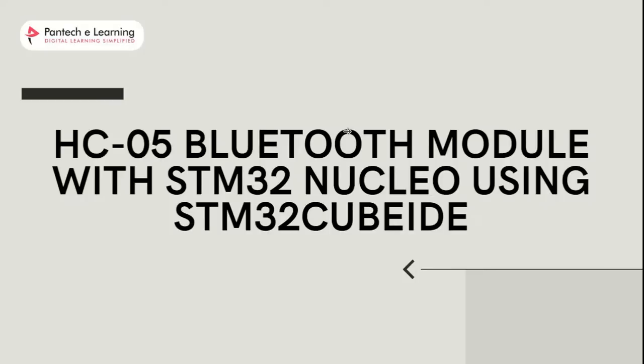So the HC-05 Bluetooth device operates on UART communication. It uses serial communication to transmit and receive data serially over a standard Bluetooth radio frequency. Therefore we will use the TX and RX pins of STM32 Nucleo to connect with the module.